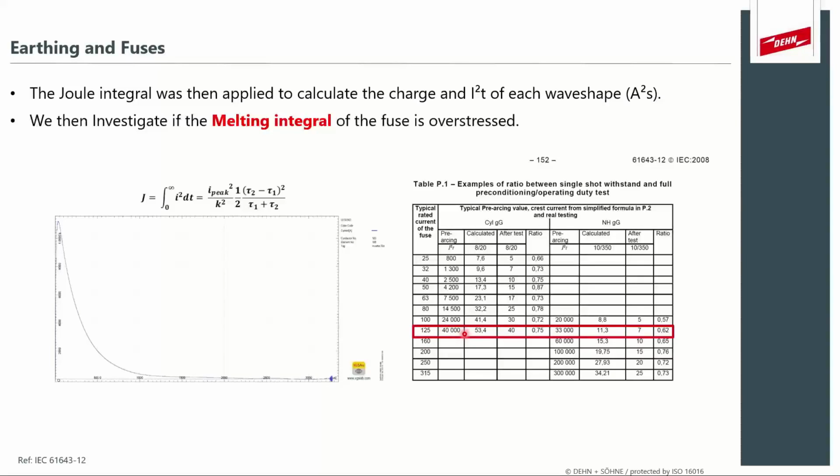Now, luckily for XGS Lab, they have ways to get this value extracted from your simulation, and that's exactly what we did. So when we wanted to see if the fuses are getting damaged, the first hint was calculating the charge, but we had to characterize it in terms of fuse terms. So we worked over to the amp²second or the I²T value.